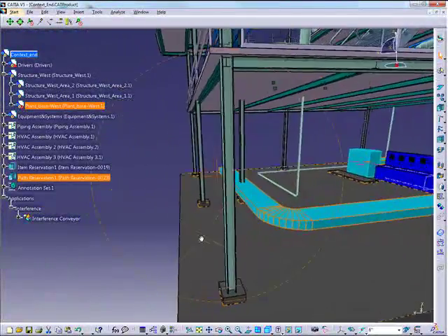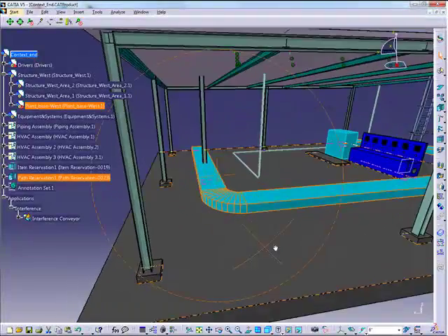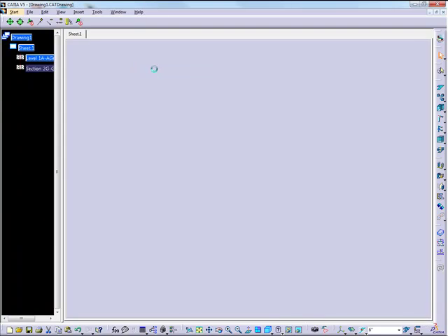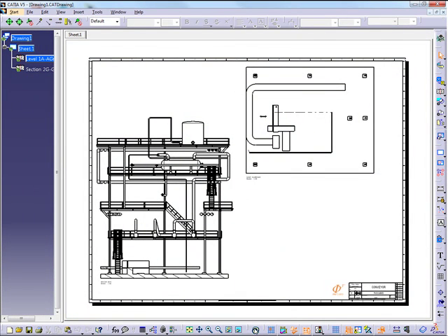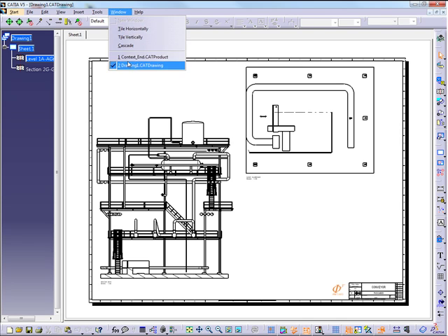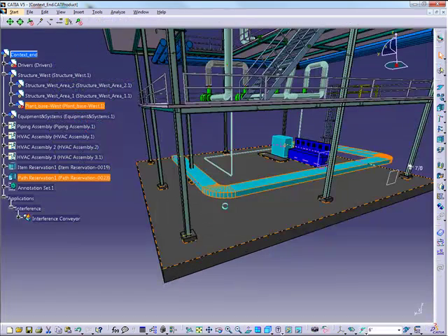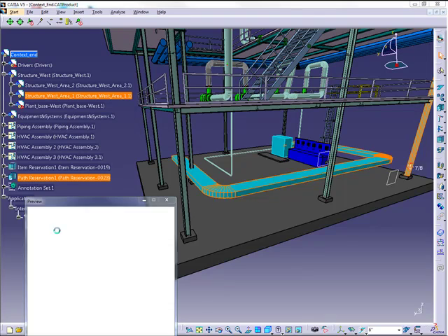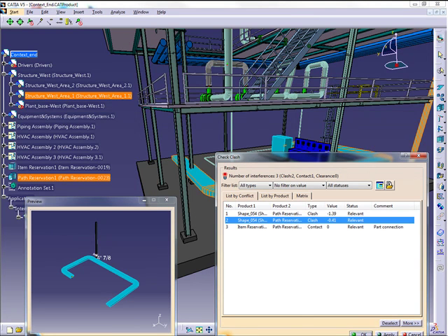So perfect, Juan. Let's go back to the drawing, update the drawing, and then we'll update a clash. Perfect. So at this point, we see the new drawing has been updated, and we see that we have a clash with one of those columns. So Juan, if you can, just go back to the model and rerun the interference check, and just exactly hit apply.